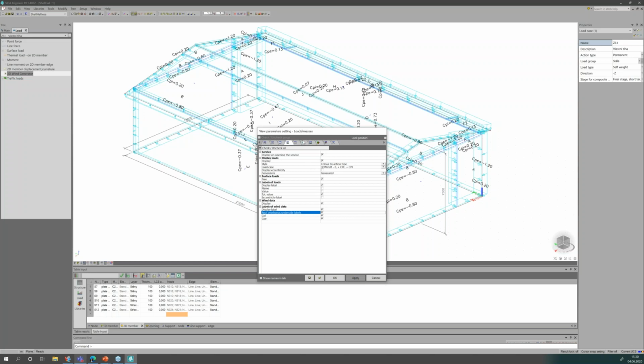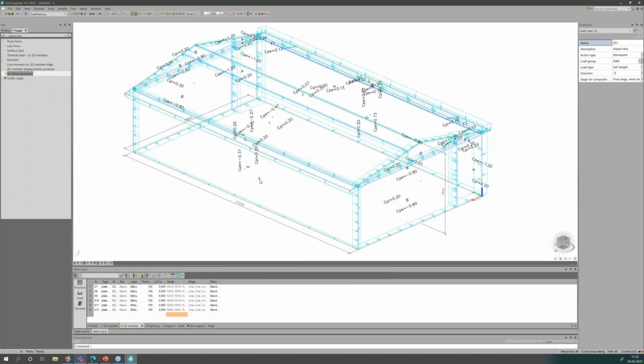So I click on apply, and now I have a pretty clear situation on the monitor to see where the zone D is, where the zone E is, and which CPE coefficient is used for the mentioned zone. What I would like to also know is the possibility to see the dimensions of such zones, like how long the zone A is.